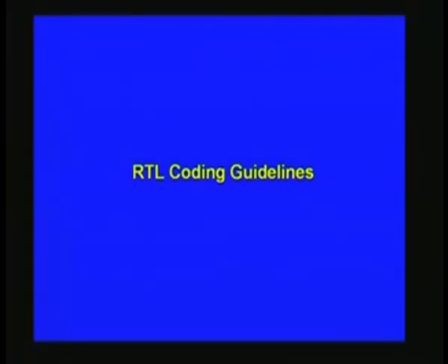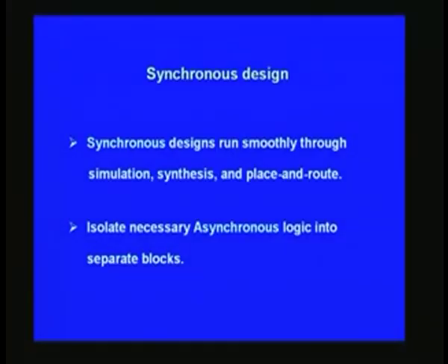It is basically a synchronous circuit design as such, which you are already used to, and it signifies the data flow and how you process the data as such. And basically it is a synchronous design which should naturally run smoothly through simulation, then synthesis, and finally place and route as such.